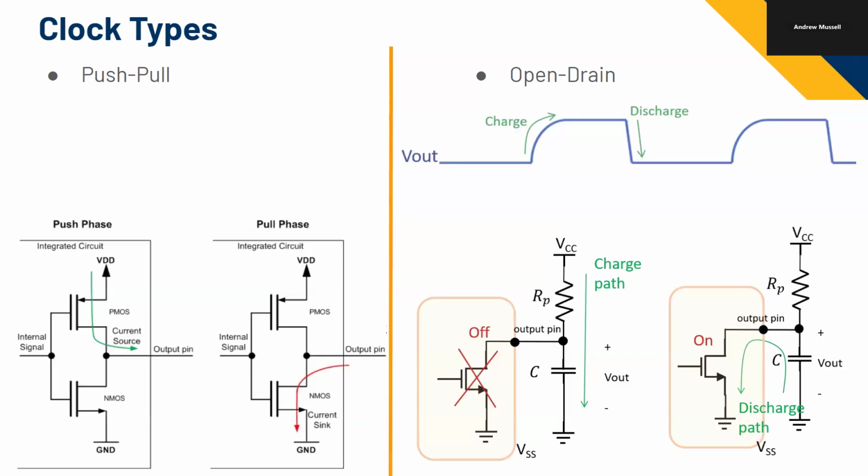But so when this is high, the VSG is low, right? Because if this is VDD and this is VDD, then this is not on. So this will be off, which is that case. And then this will be on because internal signal is VDD. So this is high. And then when this goes low, VGS is going to be off. There's going to be no voltage here. So this turns off. And then because this is 0 volts, your VSG is VDD, right? It's going to be very large. So this one will turn on.